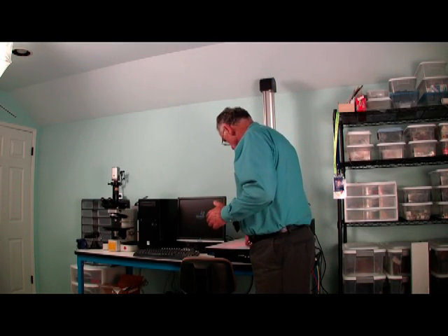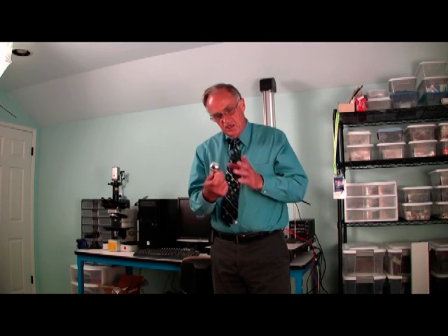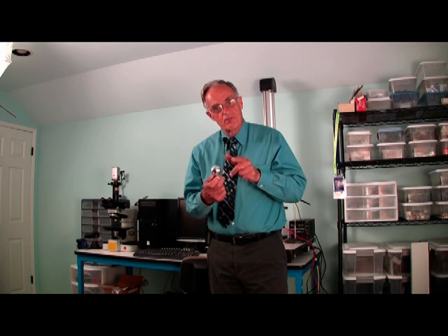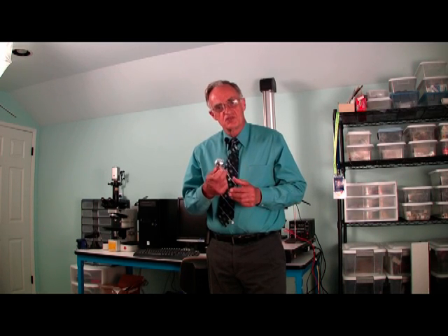Another very important property of illumination is its direction. The conventional way in machine vision for benchmarking or characterizing the direction of illumination is to use a polished sphere. Place the sphere in the field of view and image it with the camera. You will be able to see where the light is coming from as it reflects off of the sphere into the camera. Now there is distortion, but this will still work as a good method of characterization.